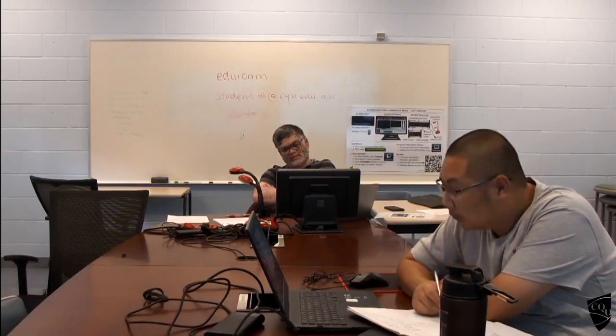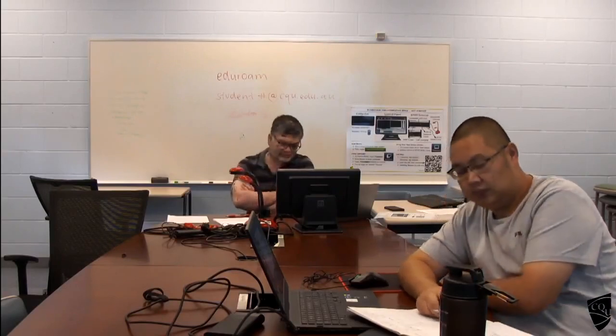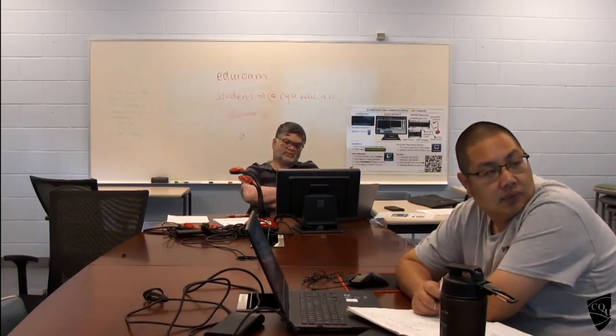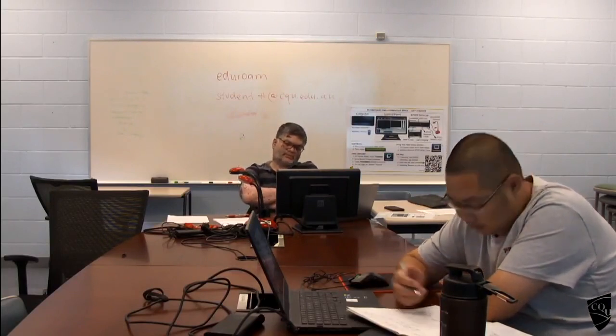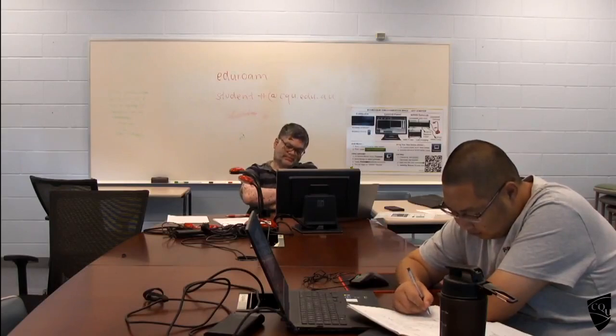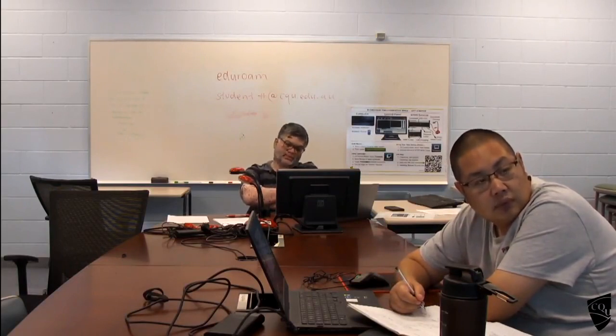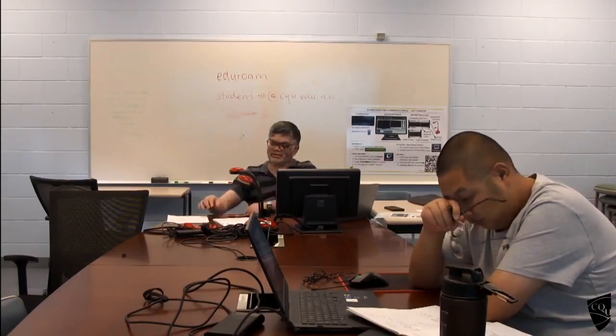So if you want to find out the deflection, the one thing you need to know is the I value for cracked and uncracked section. So that's what we discussed now, how to get that. Then you need to go to the standards. So if it is simply supported, the deflection is 5/32, so this one.